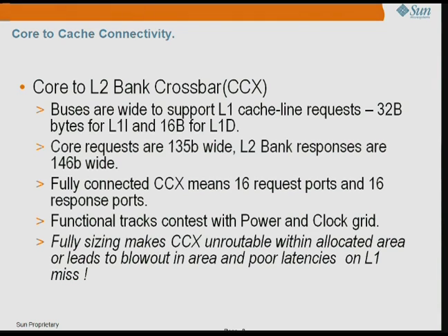So now focusing on the challenges and providing you a little more detail. I've spoken time and time again about the crossbar and how critical that is to converging on the chip. There are certain design constraints that are invariable because, for example, our core request paths are wide. There's no way we can compromise around that.